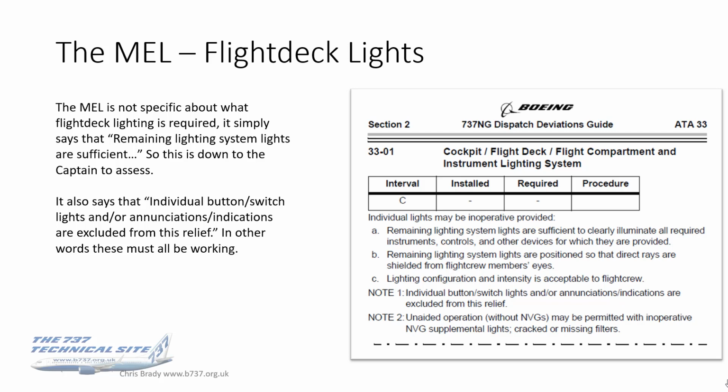Okay, let's see what the MEL says about it. It's actually not specific about what flight deck lighting is required. It simply says that remaining lighting system lights are sufficient to clearly illuminate all required instruments, controls, and other devices for which they are provided. So basically, it's down to you as the captain to assess this.